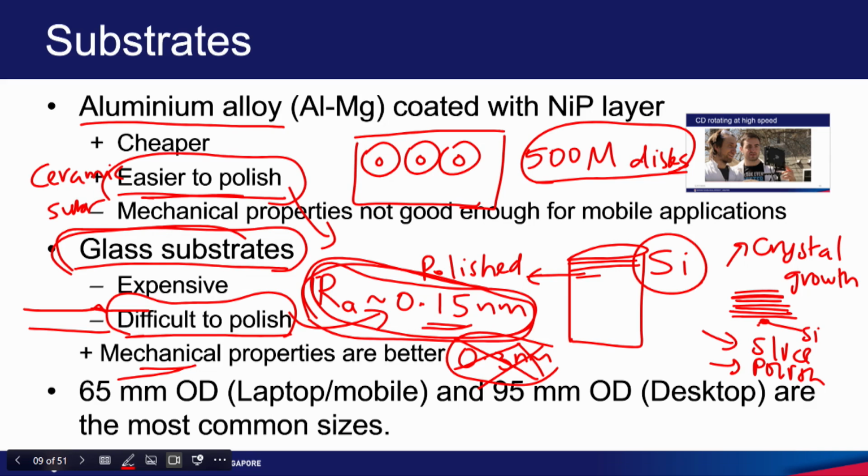There is another online question: can we revisit to understand why a high damping constant is undesirable? What I understand is that higher damping constant will result in faster alignment of magnetization along field direction and hence better speed, which is in contrary to the discussion in the sessions. There is no contradiction.